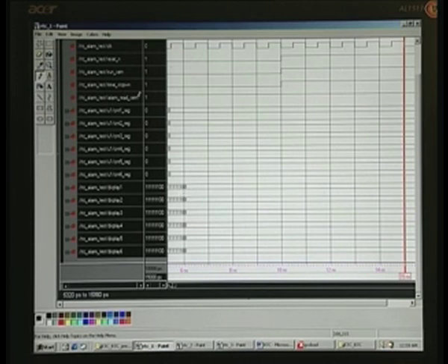So remember that all these 3 will have to be 1, that is run mode, time mode, then alarm in read mode, and this is mandatory in order that time may run smoothly, and this happens at 10 nanoseconds. 10 nanoseconds because we have taken 100 picoseconds as a time base multiplied by 100, which we have given as 100 units of time. So that gives you 10 nanoseconds.